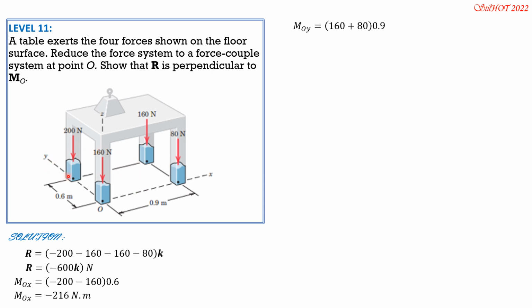This is your right thumb. These are your four fingers. So the sense of moment would be in that sense, same as 160 and 80. So quantity 160 plus 80 times 0.9. MOY therefore is 216 Newton meter.